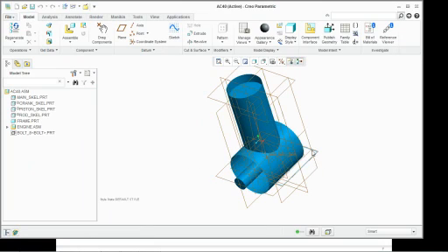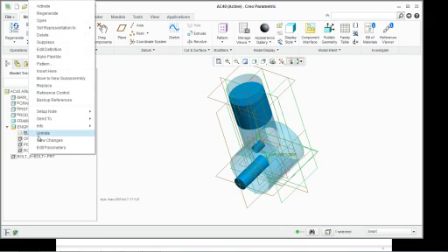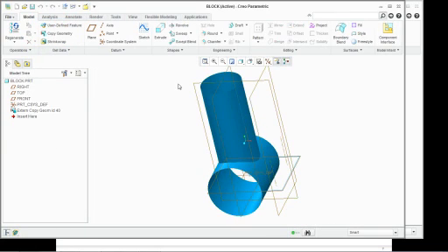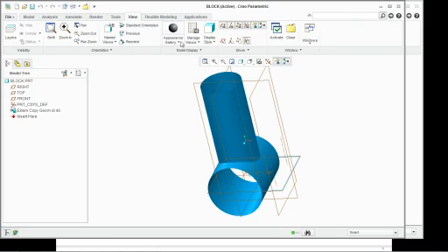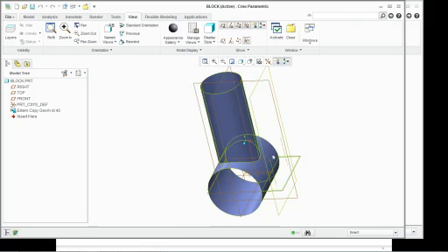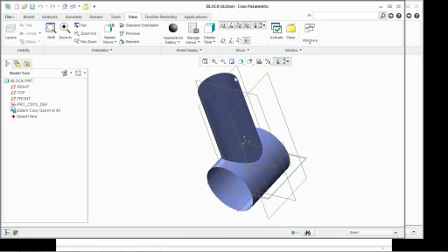What I want to do here is select this first assembly. I want to actually open the engine assembly and take the block, right-click, select open. So if you notice, it is blue. You're thinking, well, that's a skeleton. Well, no, it's actually not a skeleton. If I go to my appearances, clear all appearances, yes, remove all appearances. Notice it's purple. It's a surface.